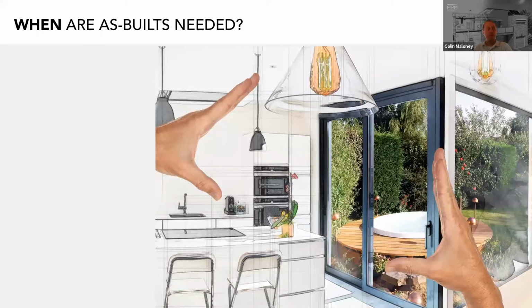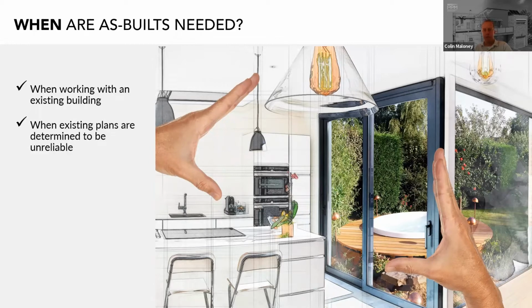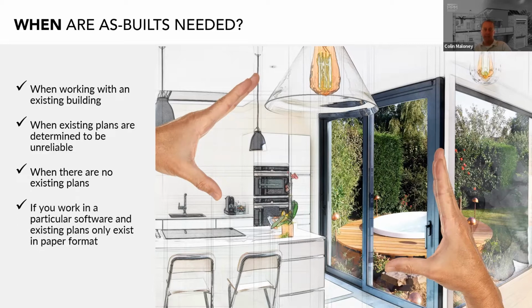So when are as-builts needed? Pretty much whenever you're working with an existing building, we need as-builts before starting your design. If the owner or client happens to already have as-built drawings, then we may just need to enter them into CAD or reformat them if they're already in CAD and confirm that the drawings are up to date. If errors or inconsistencies are found, then at some point you may decide a fresh set of as-builts is needed.